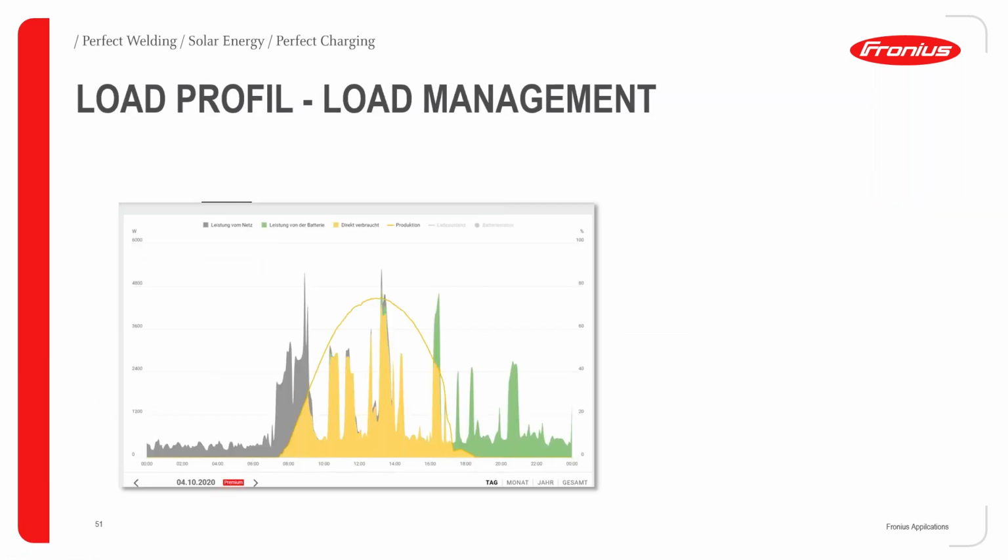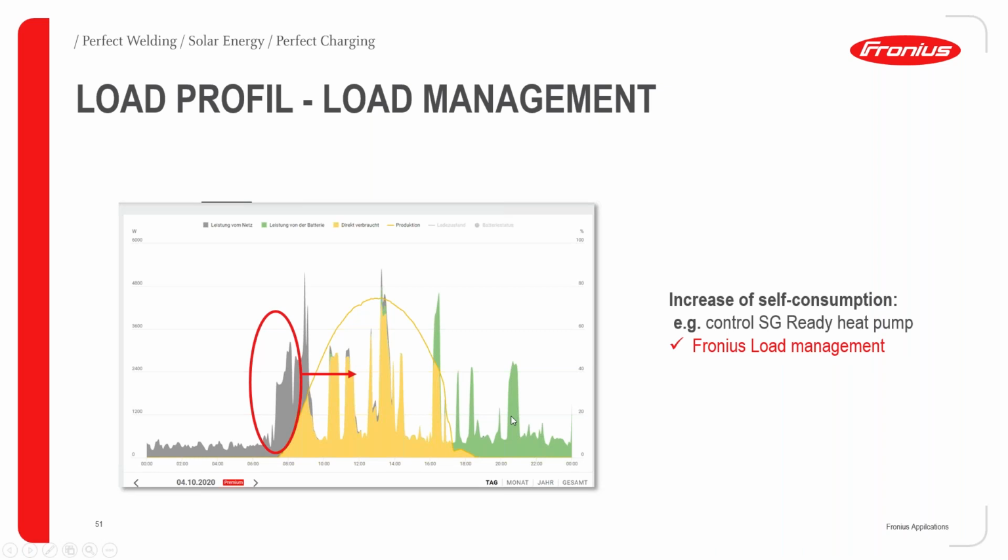And then if you have a smart meter, you can monitor the load profile. Then, okay, I can see here in the morning, 7 to 9 a.m., I have a big load. Maybe I can shift this load to a different time in the day. By that I can consume my own energy. I don't have to send the energy to the grid.